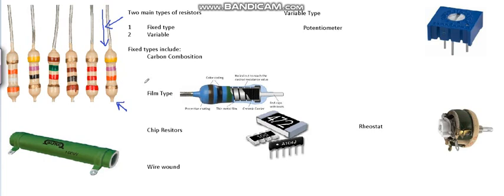The problem with these types of resistors, or any types of resistors, is if you put too much current through them, then they only have a certain wattage capability. So if you put too much current through them, then they'll get too hot and they'll burn up. Some of them will smoke. Some of them will catch fire for a little bit, and then they'll actually burn open, meaning open that they won't be able to conduct any more current.